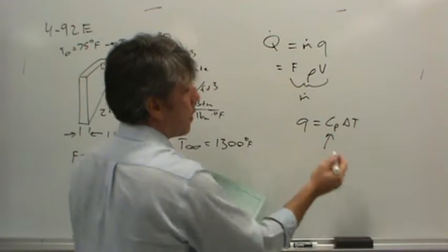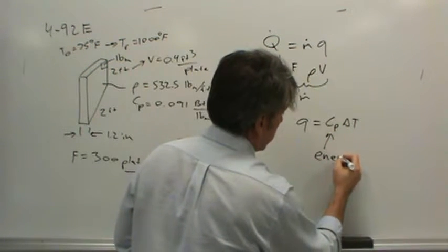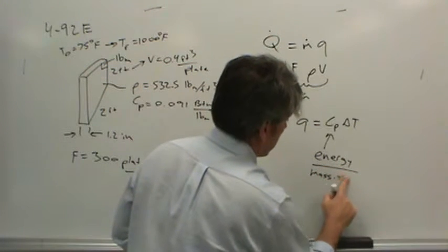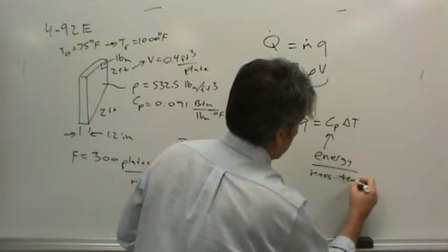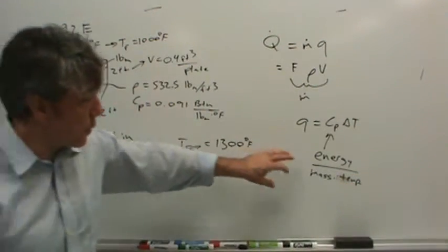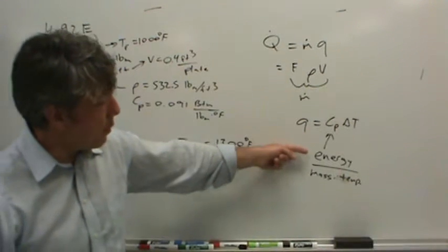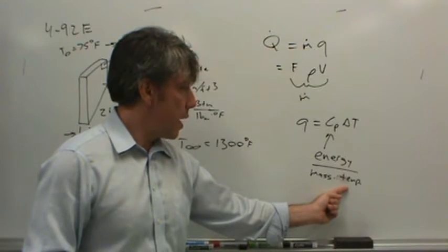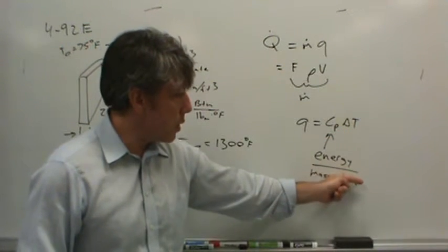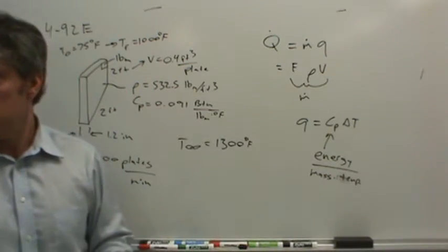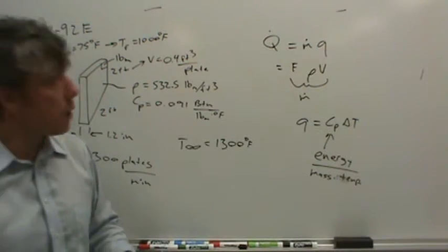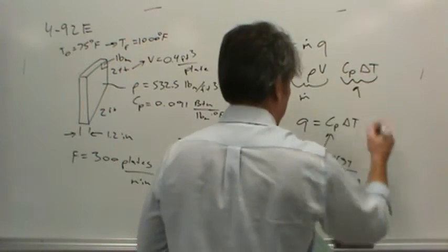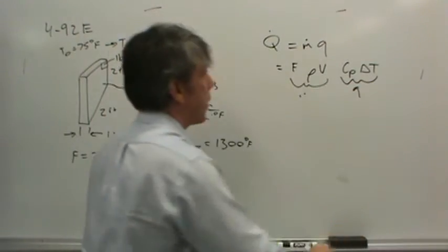Think about it though, the units of heat capacity are, or the dimensions are, energy per mass per temperature, right? And this is specific heat capacity because it's per unit mass. So it's how much energy you have to add per each unit of mass to change its temperature. Then if we multiply that by the temperature, then we just have energy per mass, which is what we want. You see how Q is Cp delta T? So let's plug that in. So Cp delta T is the way we're going to expand and solve for Q.